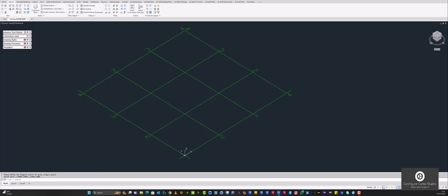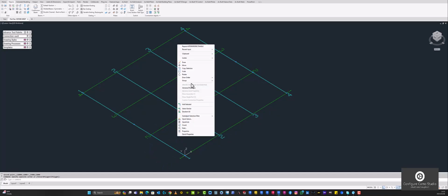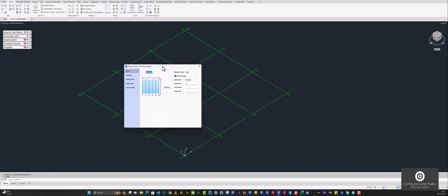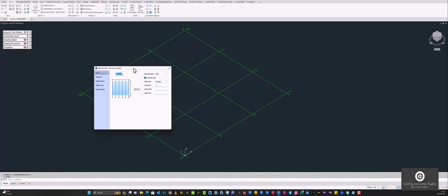As you see, you've got numerical numbers all over the grid, we need to edit that so that we've got alphabetic and numerical. So how do you add your grid line? You select one of the grid lines, as you can see, then they are highlighted as a group. So you can edit on the Y, you can edit on the X. So select the group and then right click and then go to advanced properties. This tab is the one that allows you to edit your grid lines.